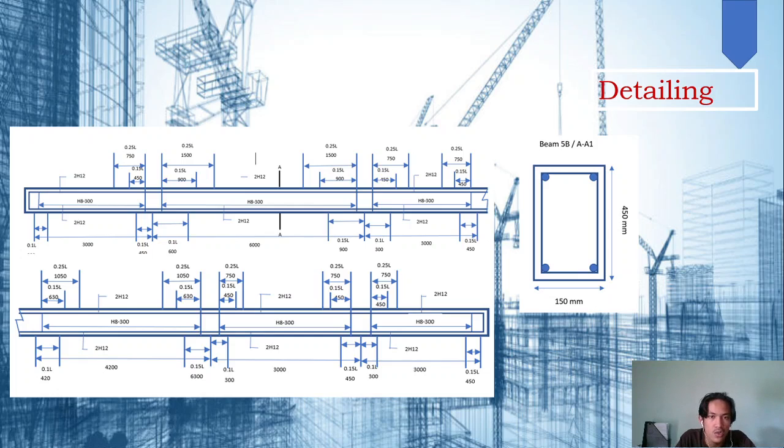Okay, so in this detailing we will use reinforcement of H12, and the shear reinforcement is H8 300.